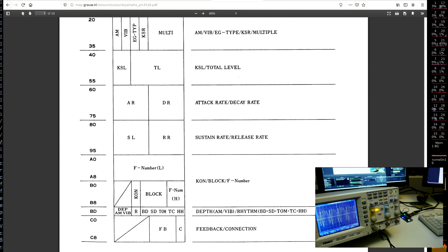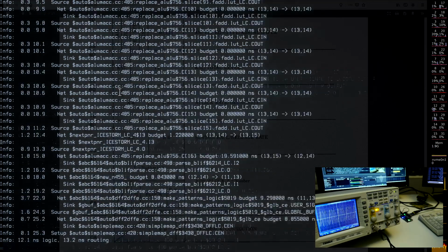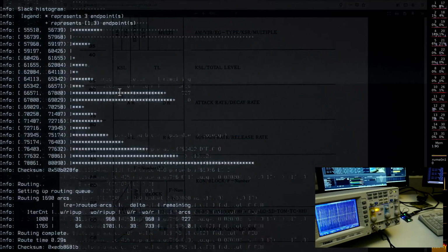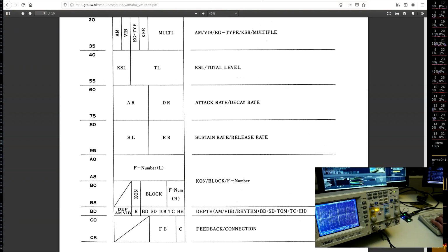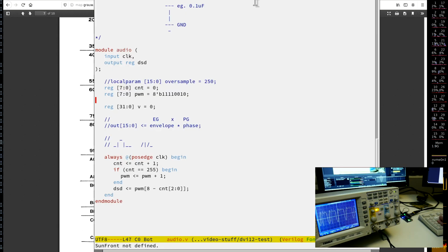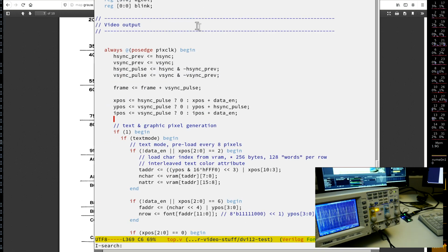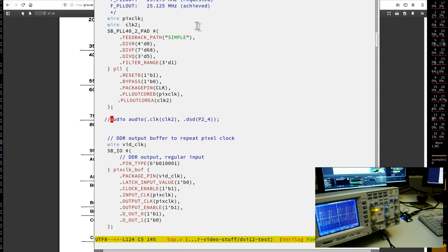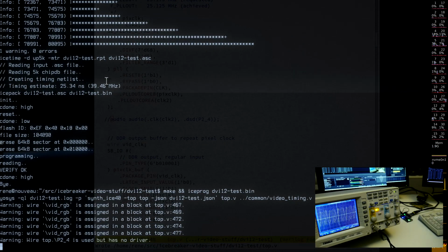This design is using, let's see, together with the VGA core, not too many, 400, so probably only some 50 or so. Hopefully we could actually, so this is 451. The easy way to count this is simply to comment this out. Audio, so if we just comment this out and resynthesize this, we should, so 451, let's see how many we get now.